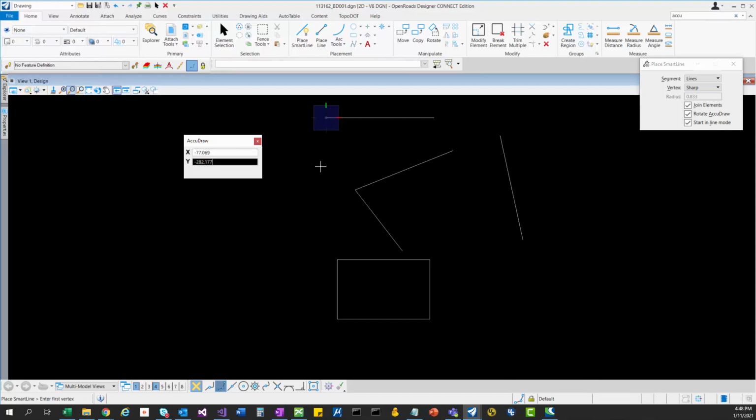So maybe I do want my 50 feet down here. All right, and my X I'll just lock at 0, right? So I'll lock those values. So now I'm going to data point. That's a left click here, and that is starting my line. So no need for a scratch line. I can start it right there, right? All right.